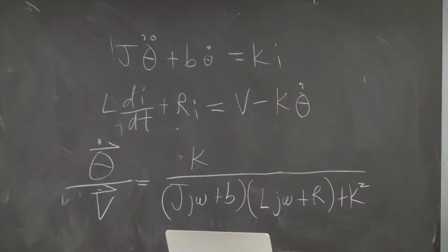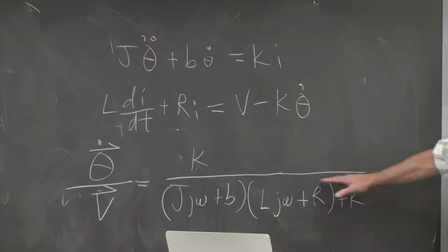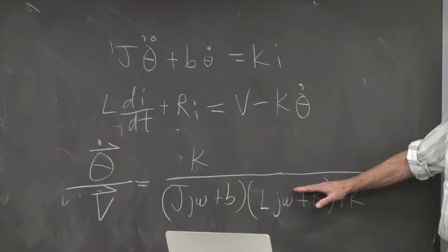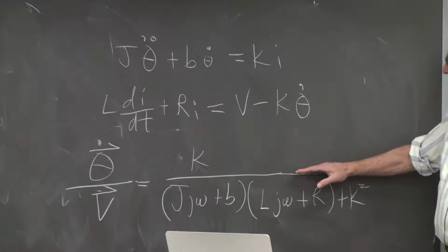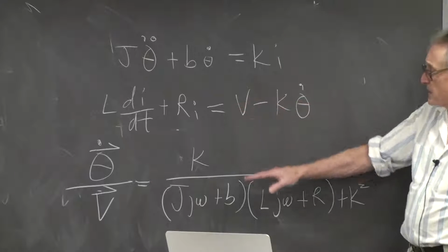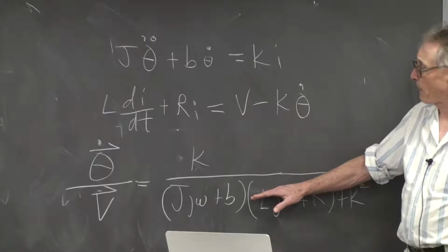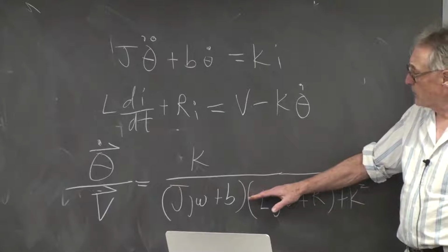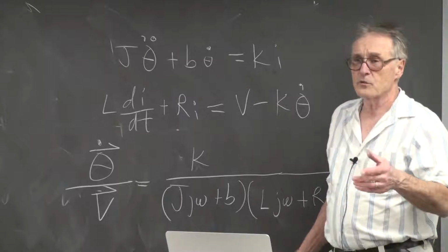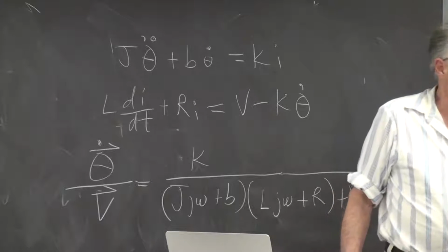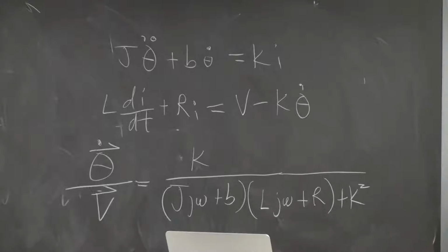So this is a second order transfer function, second order equation. Oh, this is the solution for a sine wave, of course, because really what we're doing is we're taking the Laplace transforms of this and then solving the Laplace transforms. And so we're looking for a sinusoidal solution. But this is true for any solution because of superposition in a linear system. So you can treat this as a general solution as long as superposition holds.